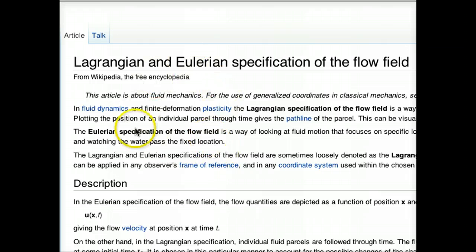And then you have an equation for what happens in every single block, right? So you're literally breaking up the space in which the fluid exists into the static grid, and then you have an equation for what the density and the velocity of the fluid in each block is, and you try and solve that.